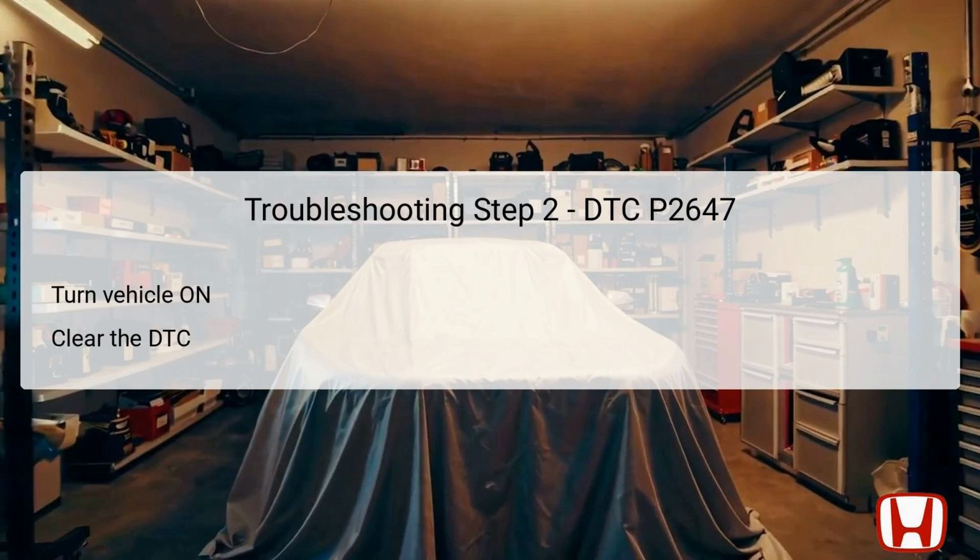Clearing the code is crucial, as it resets the onboard diagnostic system and allows for a fresh assessment of the engine's current state. After clearing the DTC, perform the VTEC test found in the inspection menu within the HDS, which checks the operational integrity of the VTEC system.